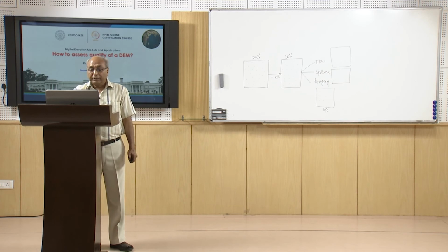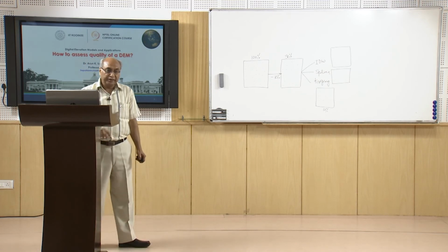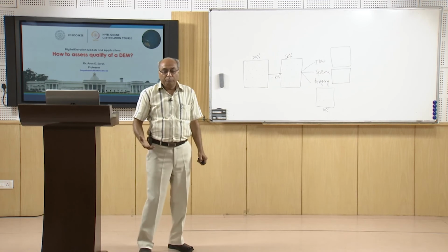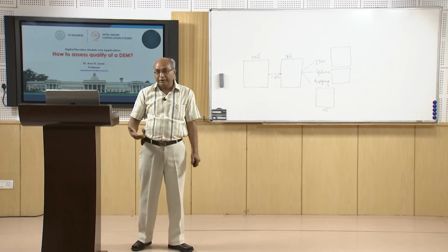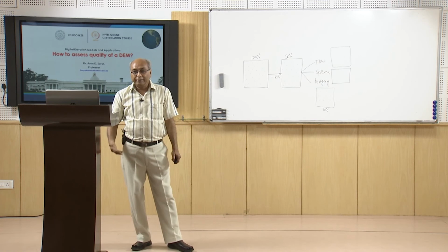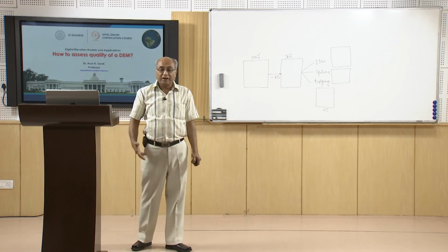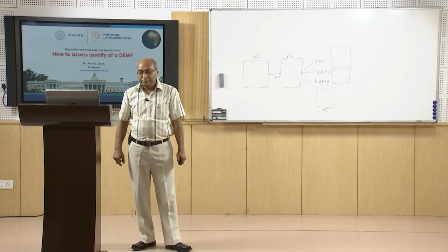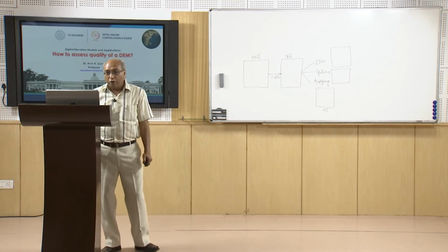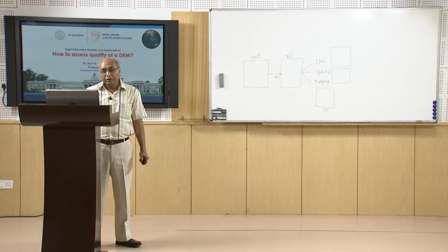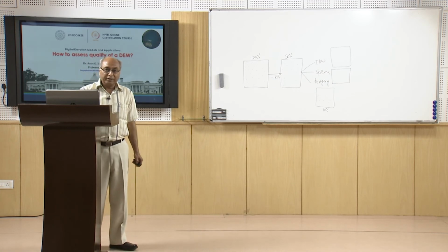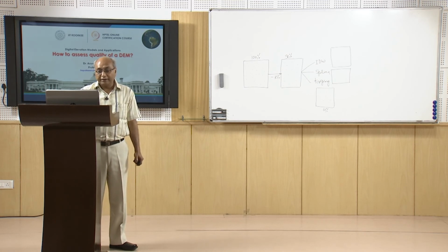But later on, employing simple GIS techniques of overlaying, with a relatively coarser resolution digital elevation model in the background, for example SRTM 1 kilometer resolution, which was also available, or maybe USGS DEM 1 kilometer resolution, you can pick the relatively coarser resolution elevation values for this 90 meter resolution data and fill the voids.